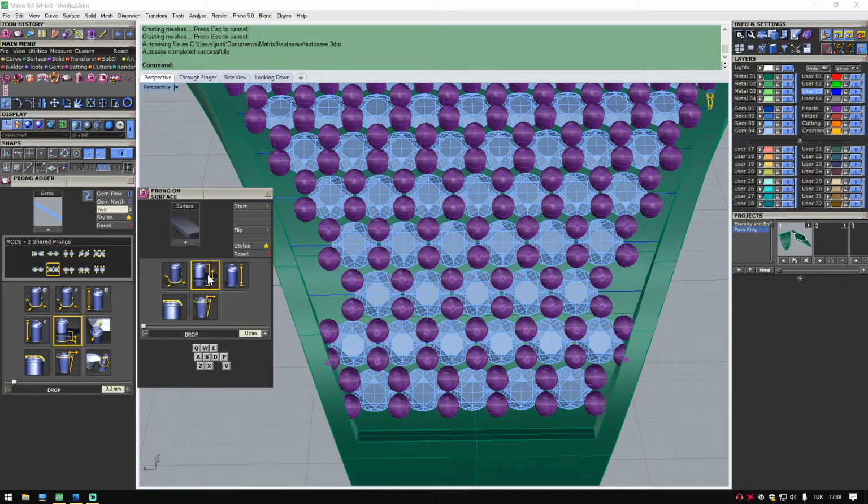So I will type, it's this box here. So we'll type 0.2. As the height, we said we will not go over 0.6 millimeters, which is this one, 0.6 millimeters. The fillet, we did 90%, so I'll do the same. And the taper, I want the prongs going straight down. So 0, enter.